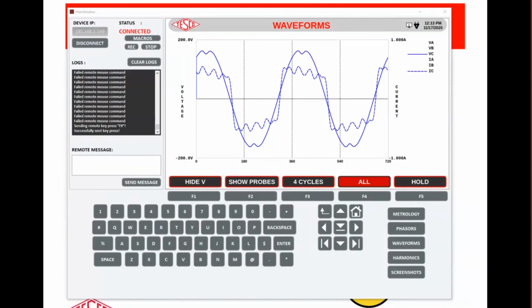The loads that came from these places turned out to be more like 60% power factor because of the highly harmonic nature of the loads. And so not only were they not getting billed, they were blowing up pad mounts.